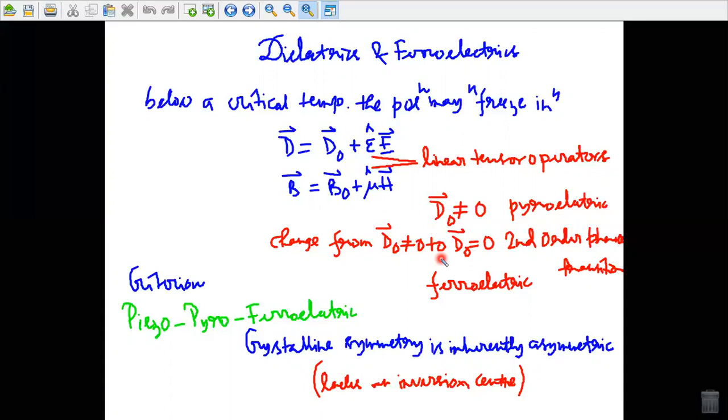It can be shown that ferroelectricity is possessed by crystals which lack a center of symmetry. So all ferroelectrics will be piezoelectric, but not all piezoelectrics will be ferroelectric. Such an example is quartz. Actually, the occurrence of ferroelectricity is interpreted to be the result of a polarization catastrophe.